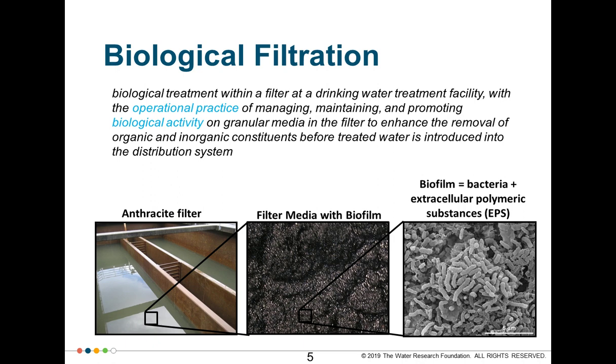And that's because the biomass on the surface of the filter is typically very small. The biofilm depth is usually 10 micrometers to up to a millimeter or so thick, so it's typically not visible to the naked eye. Instead, if you look under a microscope, you can see bacteria populated on the surface of the media.